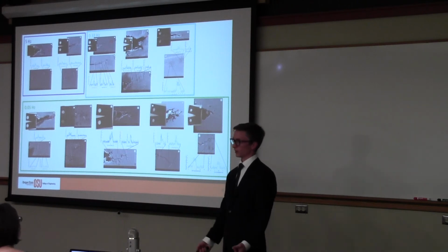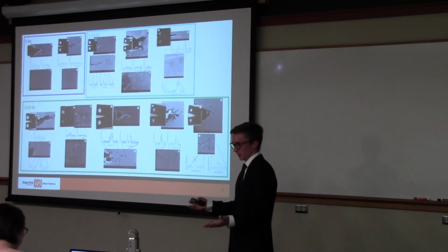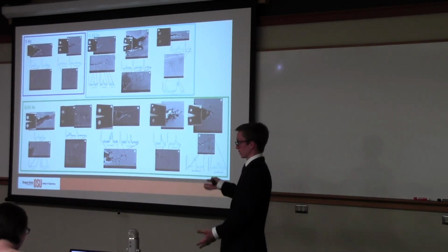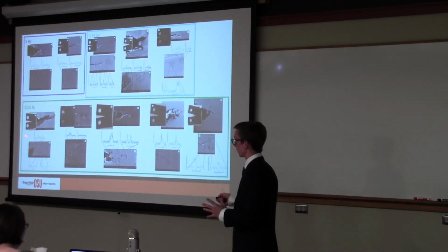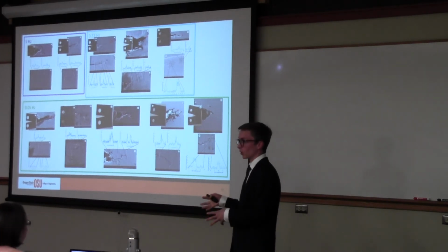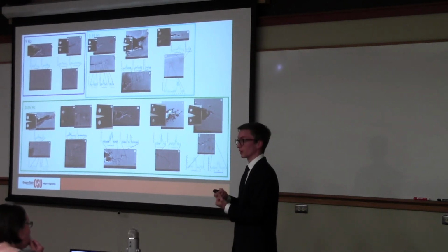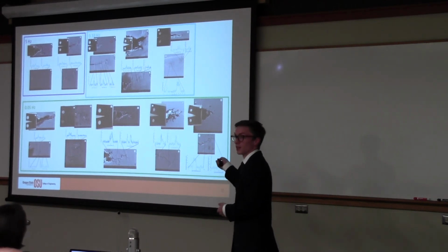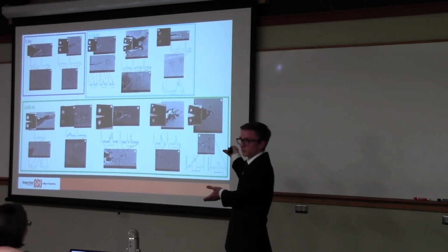In impure helium, the assumption that I want to make, and that some calculation can hopefully support, and some work needs to be done for this paper to be published, is that the diffusion of oxygen through that protective oxide layer in air is at least equal to the oxygen in an impure helium environment. So the damage that we're measuring in air is at least as bad as the damage in helium. We want these measurements to be conservative for that application.